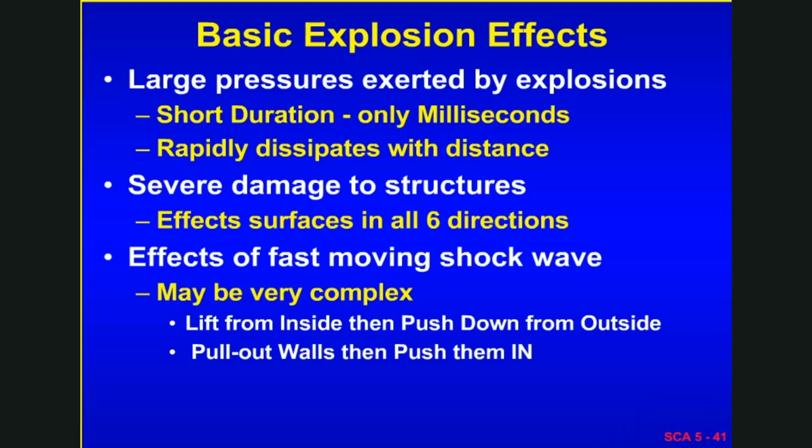These pressures are very, very large, thousands of pounds per square inch in some cases. They're of very short duration, and they rapidly dissipate with distance. They do severe damage to structures, mostly on the surfaces, and they also have a very fast-moving shock wave that can be very complex. There have been people that survived in these structures if they just happened to be around the corner from where the blast pressure is acting. The blast pressure almost acts like a flashlight, if you will. If you're in the shade of the pressure, often you can survive.